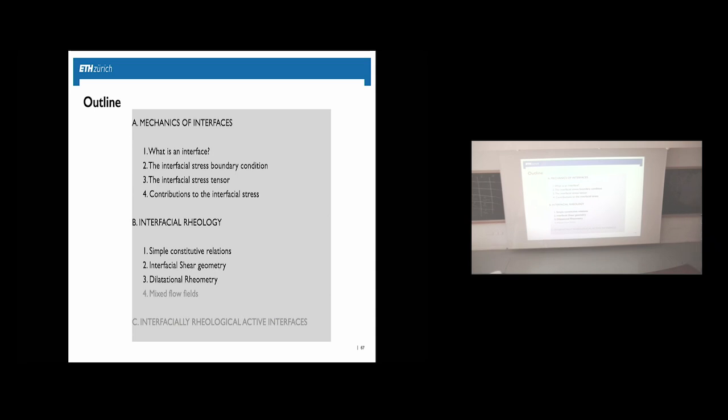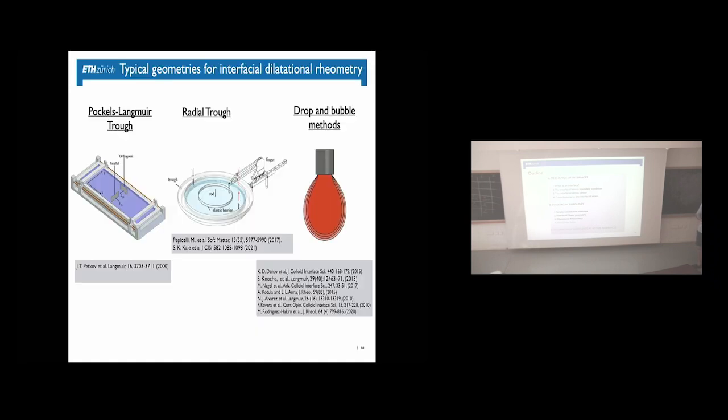If I talk about emulsion stability, if I'm making droplets, I'm trying to create interface, right? If I have coalescence, I have to break a film and compress the area. So the most important deformation mode most of the time is dilation or compression. It's conservation of misery all over, right? The one thing that you want to measure really is more difficult to measure, and dilatational rheometry is not instrumentally more difficult, but it's conceptually more difficult because now you have mixing of these thermodynamic effects and mechanical effects, and that's annoying.